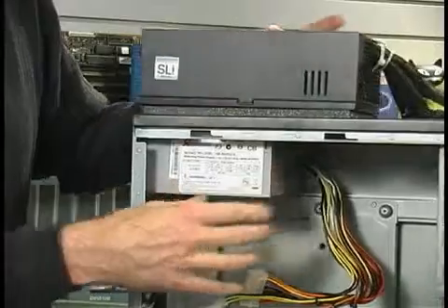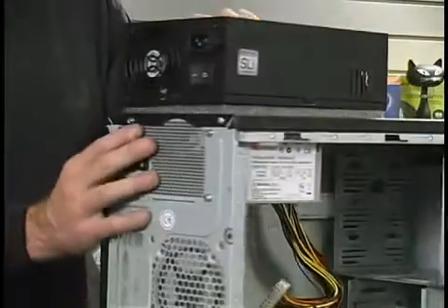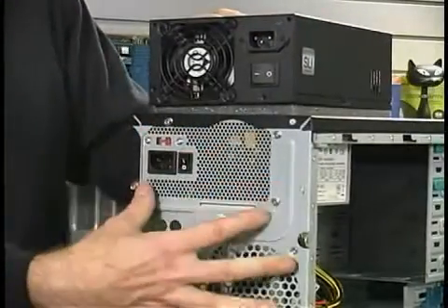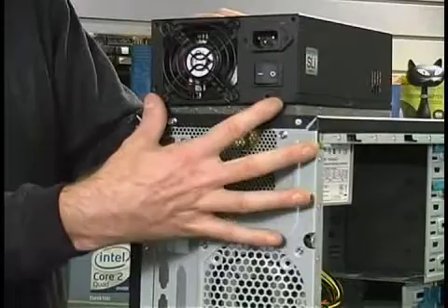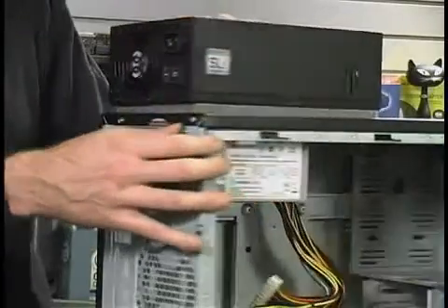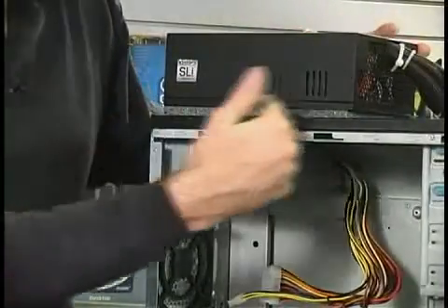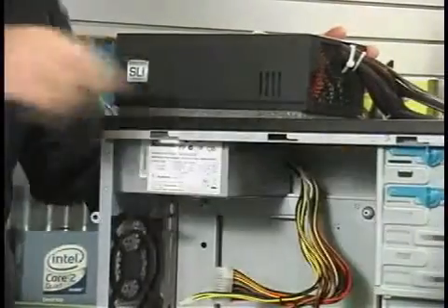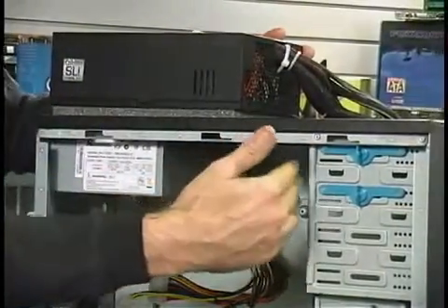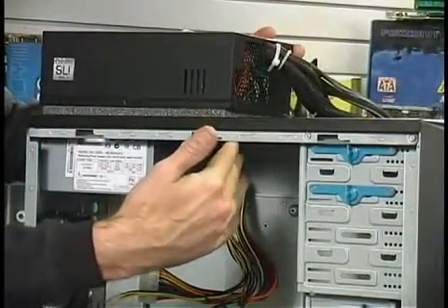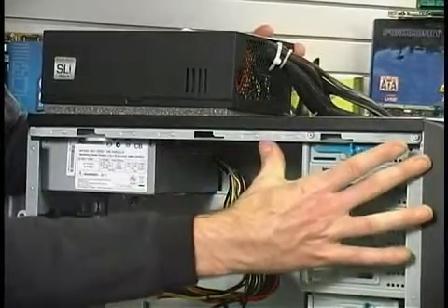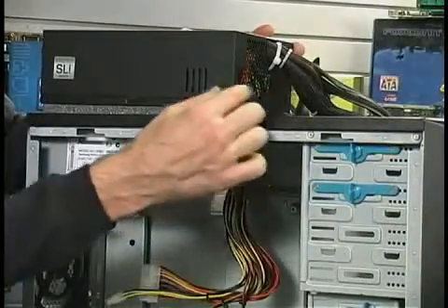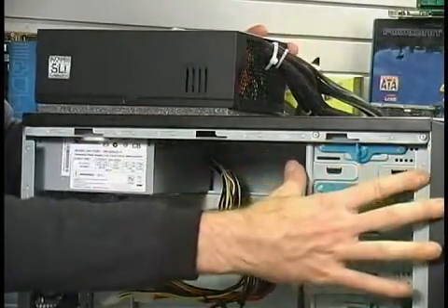I could take this out. The screw holes and everything are identical. 4 screws hold this in. The same 4 screws would hold this one in. The only issue is that I need to make sure that the case is long enough so that the optical drive will fit in the front. And in this case, as in most of them, it actually will. Most of the optical drives are shorter these days anyway, so there's adequate room between the end of the power supply and the optical drive.